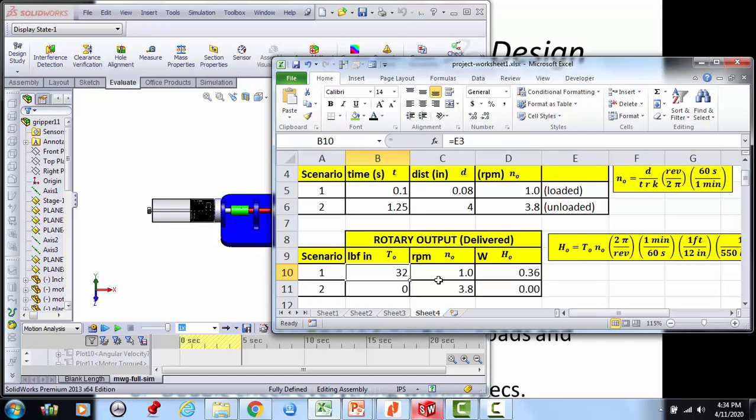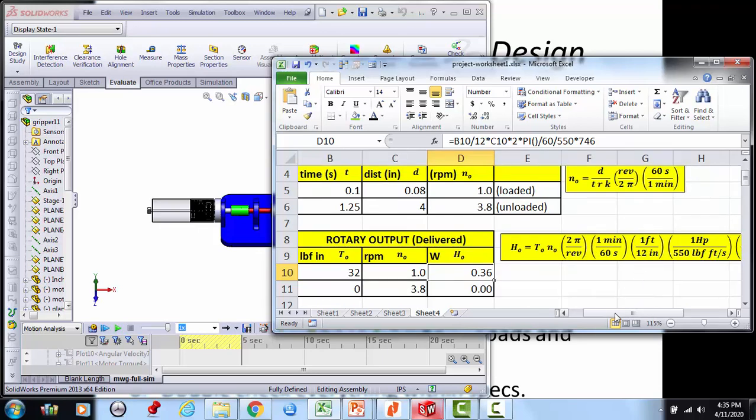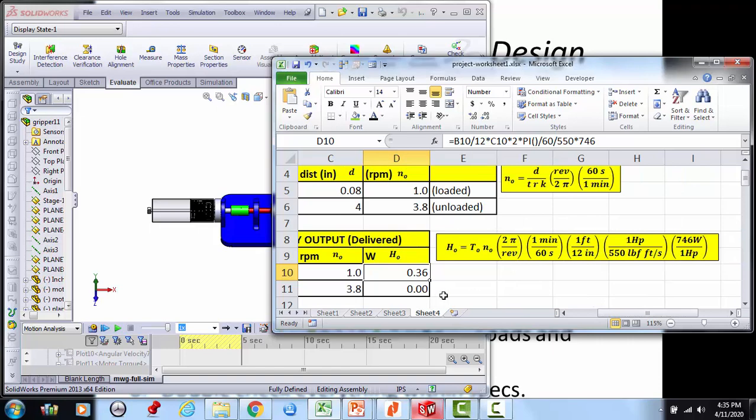That is what's going to the worm gears, both of them, and I'm rotating those gears at 1 RPM. And I want to make sure I know what the power is, and the power is a simple function. You're going to take the torque in inch-pounds multiplied by the speed in RPM, and then of course you have the necessary unit conversions.